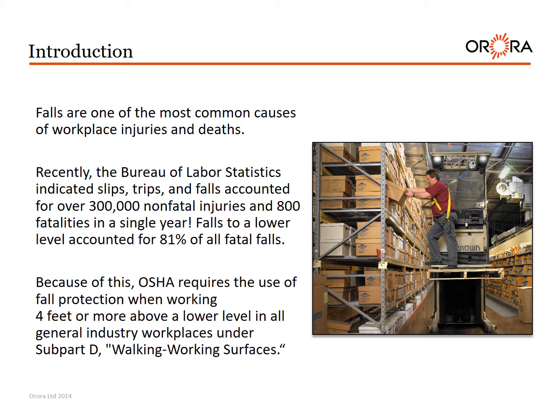Because of this, OSHA requires the use of fall protection when working 4 feet or more above a lower level in all general industry workplaces under Subpart D, walking working surfaces.